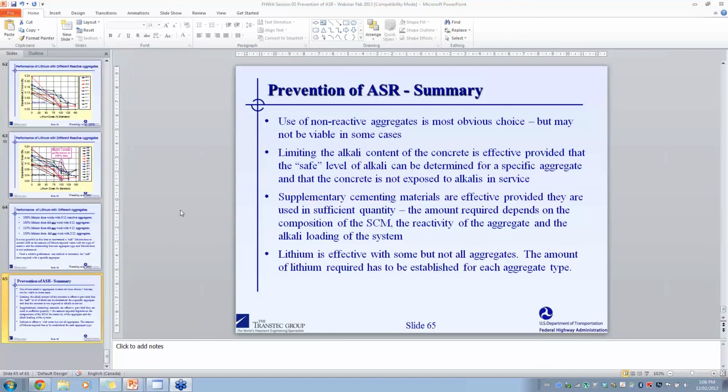Okay. The next question is, what is the aggregate type and what mineral is the culprit causing expansion at the Mactaquac Dam? The aggregate's a graywacke type aggregate, graywacke/argillite. So the reactive component is basically strained quartz, and maybe some microcrystalline quartz too. But essentially, it's predominantly strained quartz.